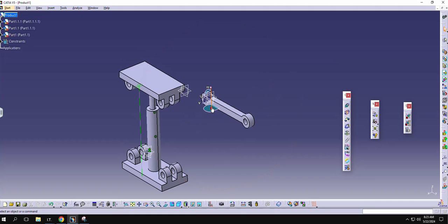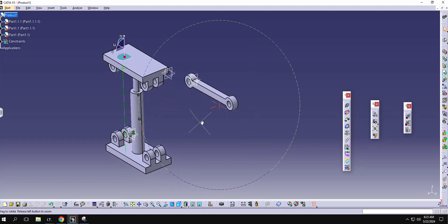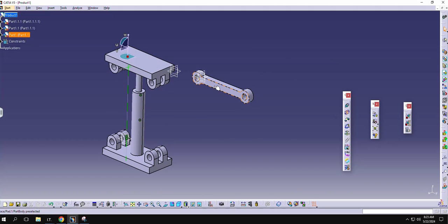So compass can be anywhere, but it needs to be moved from its standard position and kept anywhere on the assembly. So let's say if I have my compass right here somewhere, until I single click on that particular part, until it's green, it means that compass is not active. Once it is active, then you move the compass and you only control the part that you have selected, not every part. So this is one part.